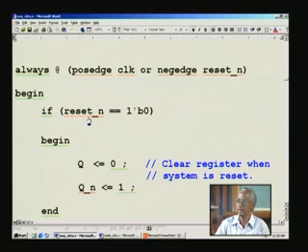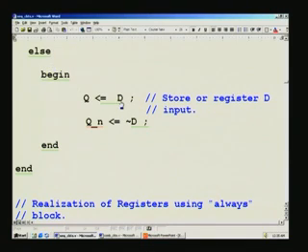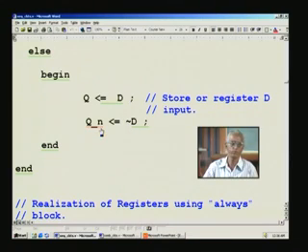This is done right at the power on stage, and there are two outputs Q and Q underscore n, which you know as a D flip flop, and you can initialize Q to 0 and Q underscore n to 1 here. And then in the course of normal working of the D flip flop, you just assign whatever is in D input to Q, and inverted D to Q underscore n. But unfortunately this creates two flip flops when you look into the synthesis tool later on. So, a way out to decrease the count is to put this as an assign statement outside, and have the same result, only an inverter will be used. That may be a better approach.